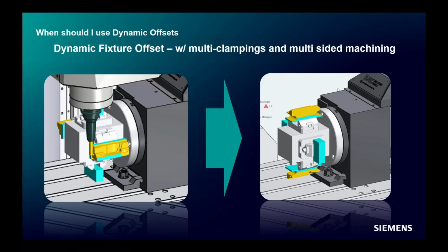So we were flipping it maybe 90 to get to the back. We were flipping it at a small angle to machine the face of the putter because the face of those putters are raked at like a 3-degree angle or so. So once you start moving this around, this is where the fixture offsets become very handy.